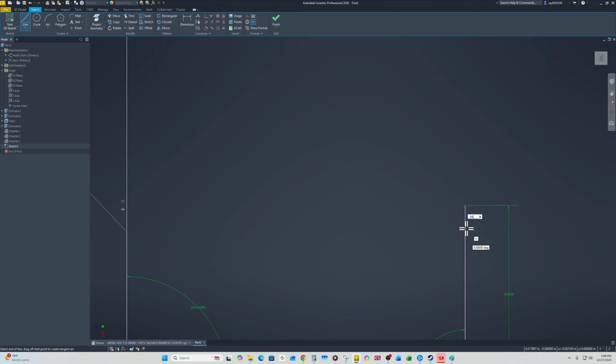We're just gonna, like I said, make a template. I don't know what the dimensions are. I gotta go back because my memory is really bad. I'm gonna do tab, and I'm gonna do 0 because it's going back. Tab, and enter. And then I'm gonna make a line towards the left, and I'm gonna make sure it's half of 60 degrees because the thread is 60 degrees, and we're referencing half of it. So we're gonna do 30 degrees.